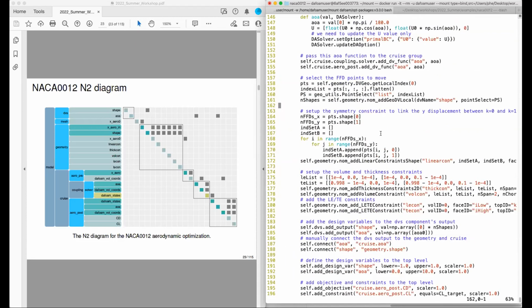So if you remember in version 2, when we add a design variable, we use this addGeoDVLocal. We can prescribe an axis. So in this case, we can just say this axis equals Y. By default it is Y, but if you want to change it to Z, that's okay. And depending on the case, you just add this here. So if you're not quite sure what the syntax for this key is, you can always search for this function in the MPhys repository. I think I have shown you the open source address for the MPhys repository.